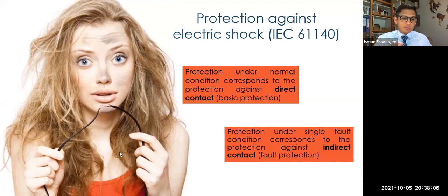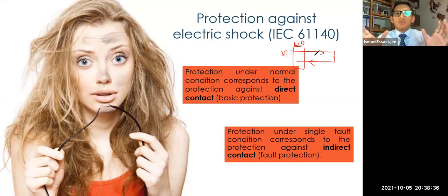If we have a fault, a fault current that was supposed to be flowing through you, the RCD is going to detect this imbalance between current coming in and current going out. This is your meter, and this is the RCD. It is just monitoring current going into and out of your equipment. Okay, this is your equipment. If 10 ampere gets in, 10 ampere gets out, it is going to record nil because it is working on the difference.